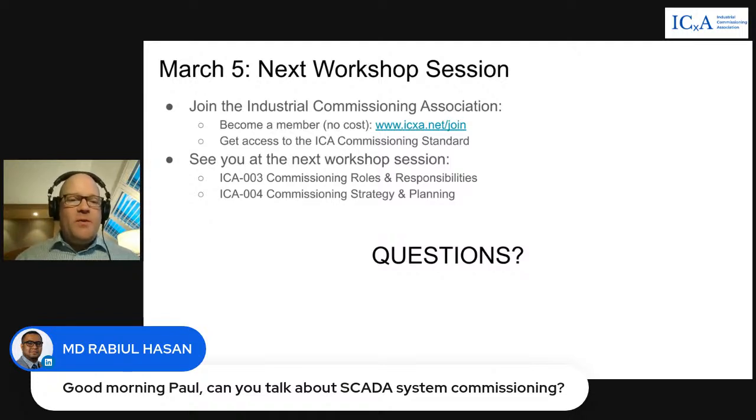The better way to do that is to do that integration in the factory with integrated factory acceptance testing to make sure that your control and protection cubicles, your communication cubicles, your SCADA cubicles, that these things actually function in the factory, both hardware and software, before they are shipped to site. Now, everybody's always in a panic, right? And they want to ship the hardware to site so they can start installing it on site. That rarely ever saves any time.